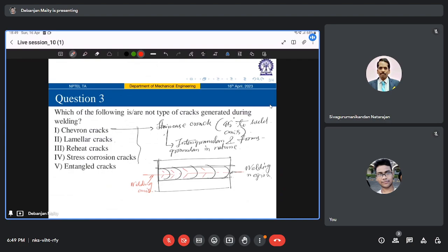Whenever there is formation of this iron carbon eutectic ledeburite, at 4.3% of carbon, that leads to this liquefaction cracking if your heat input or preheat or both are too high. Such conditions are basically employed to prevent the formation of brittle martensite also.